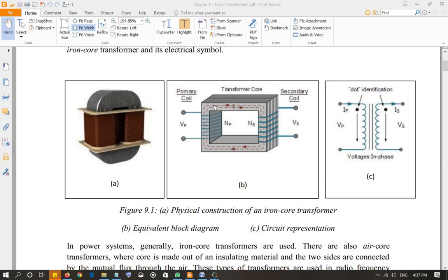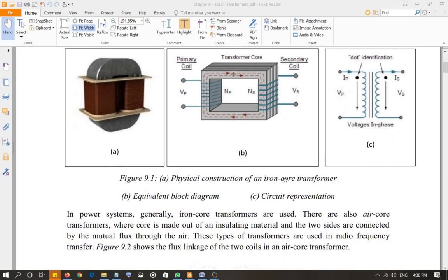and then the sinusoidal flux is going to go through the iron core as well as through the air. But since the iron core can carry more flux, has less resistance, in this one it's going to go through the iron core and is going to be linked with the secondary coil. And once again, when the time dependent flux is linked with the secondary coil, a voltage will be induced on the secondary side per Faraday's law of electromagnetic induction. So that's the basic working of the transformer.